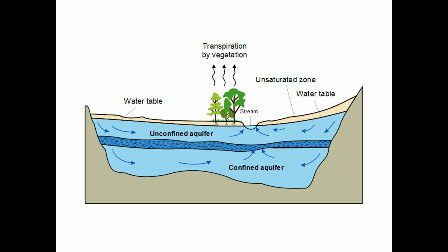So here's a cross-section through a site, and what do we have here? We have recharge coming in, rainfall comes down. It's not illustrated here, but you would have recharge coming in. So that would be an inflow. And we have a stream in the middle. So the recharge that's coming into the system would eventually be flowing towards the stream. So this stream would also be a boundary condition. The water level is fixed at that stream.